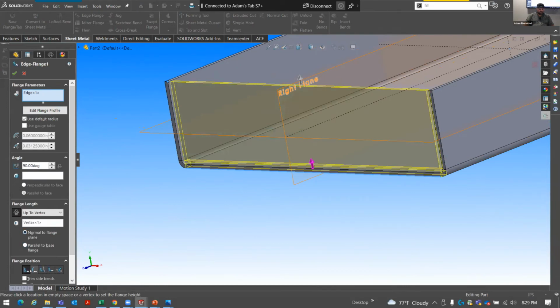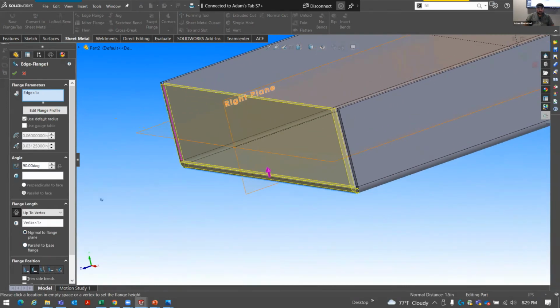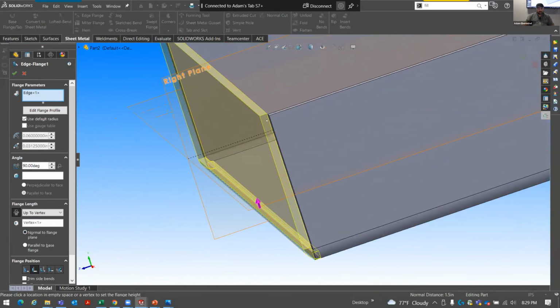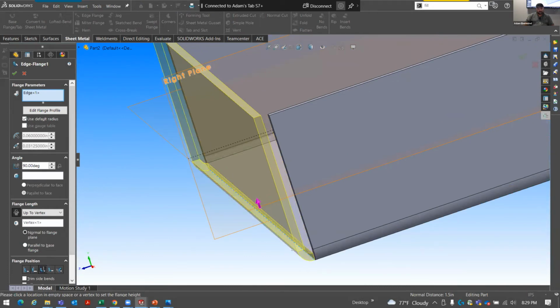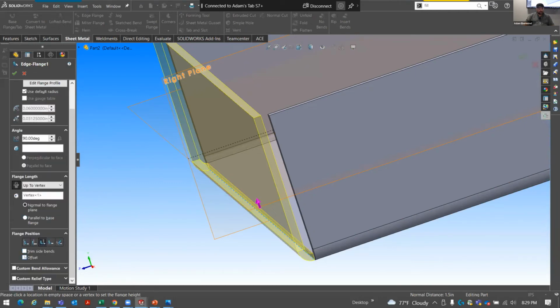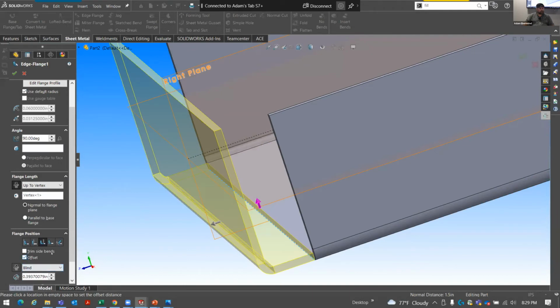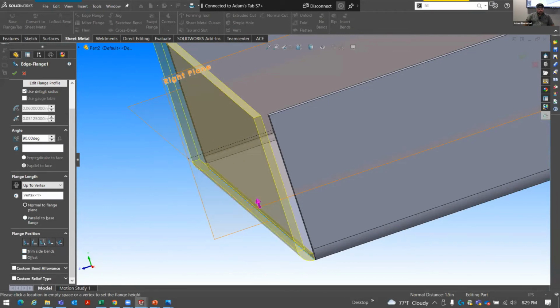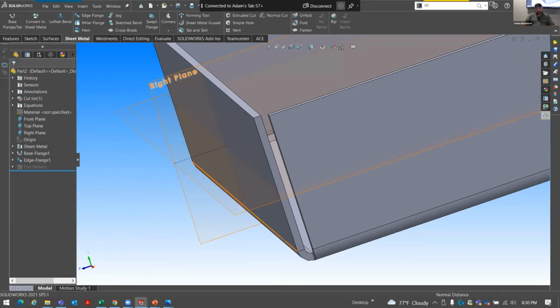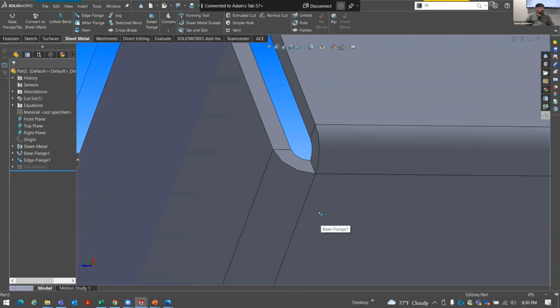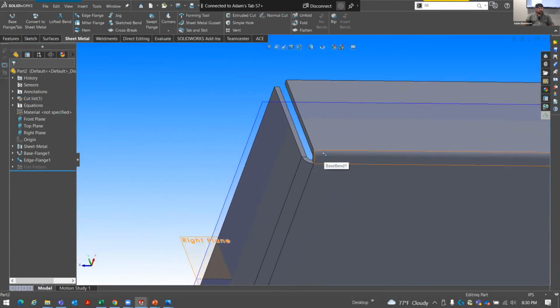which, that's inside the face, right? This brings you out just enough to where the inside face comes out. So from the inside face to the end would now be the 10 inches. This brings that and the radius out, right? And we can also even offset the flange and name how far we want it to go out to, right? So if we just come back and take the offset off, we run it here, we don't have any issues at all with that edge there. There's no tearing of it, right? And we can build onto that. We can add some more features, but a lot of times people like to close these corners up, right?